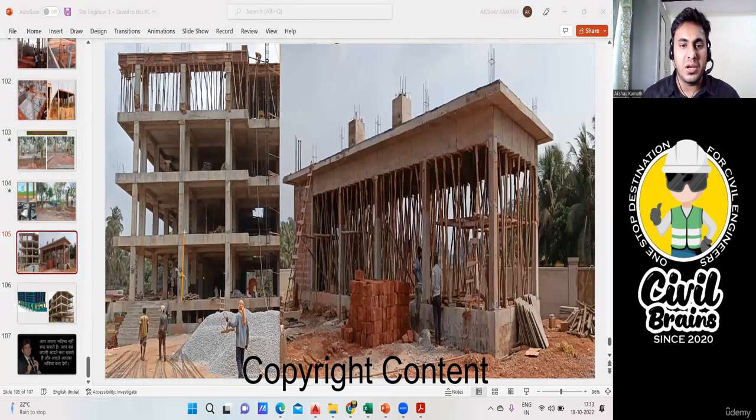First floor is done. Now I'll come to the first floor. I'll again find the height of this column. This column height I'm going to find, up to the top of the slab, that is, up to the top of the second floor slab. Then again the column shuttering, the column concreting, and then the second floor roof shuttering and slab centering I'm going to do. Getting my point? This is how we need to proceed.